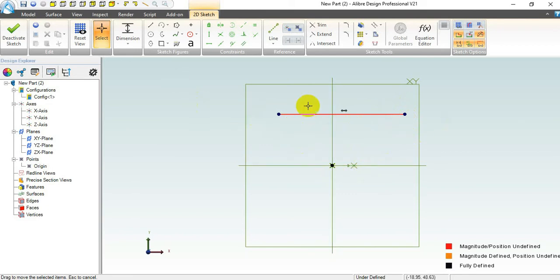Now let's change another thing here. Let's put a dimension in. Let's make this line 100 millimeters long. Let's go over here to dimension. Left mouse button click, and we'll select that there. Left mouse button click, drag this up somewhere up here. It's not really critical where it goes. Click it again, and it comes up with a little dialog box, and this is like a spin box thing, but if it's blocked blue like that, I can type 100. At the moment it's 96.9 whatever. We'll just type 100 straight over the top of that, and we'll press enter or press the tick button.